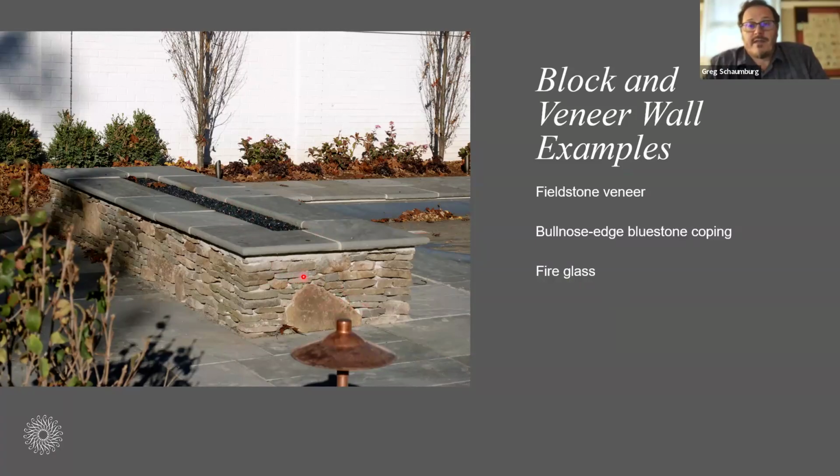Yep. So behind this, actually, this was built with fiberglass and a natural gas diffuser. So it's a natural gas line that runs to it. If it was an open flame, and if the flame was down and exposed to the heat, we would likely have put a fire brick on that part of it. Because this didn't have that, and the gas was actually up above, there's fiberglass here, and behind this is a concrete masonry unit and then capped. So essentially you have the structural material behind it and then the facing material outside of it. So it's a regular old concrete brick. I mean, block, like a big one. Yeah, a regular 8x16 CMU.